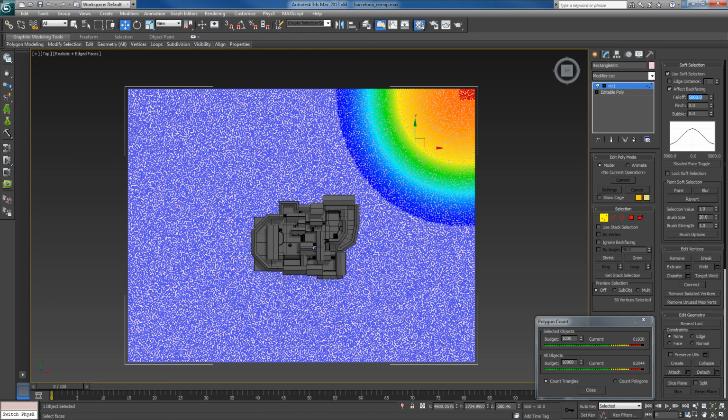Soft selection is pretty common in most applications. Quick explanation is a gradient between 0 and 1, which creates the ability to deform shape in an arc. We also have access to different types of brush options and curvatures, but we won't go into that. Read up. Okay, so falloff is not high enough, so let's try 6,000.